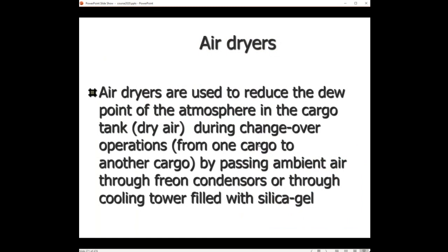Also, when you prepare your cargo tanks for the loading of ammonia, you will use dry air and not IG, since IG and ammonia react with each other, and they will create a white powder which might contaminate your ammonia. So that is to avoid. That is one of the reasons why you have air dryers on board.